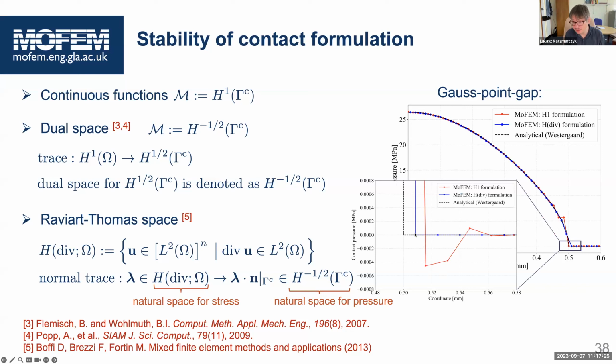There is no other option. And then you see this corner where we cut the corner over here, because our contact front is in the middle. Fine. When you refine the mesh, that error will disappear. The area integral of the difference between the dotted black line and the blue line will get smaller. But our error is not polluting the rest of the solution. This is the key. That solution is stable.